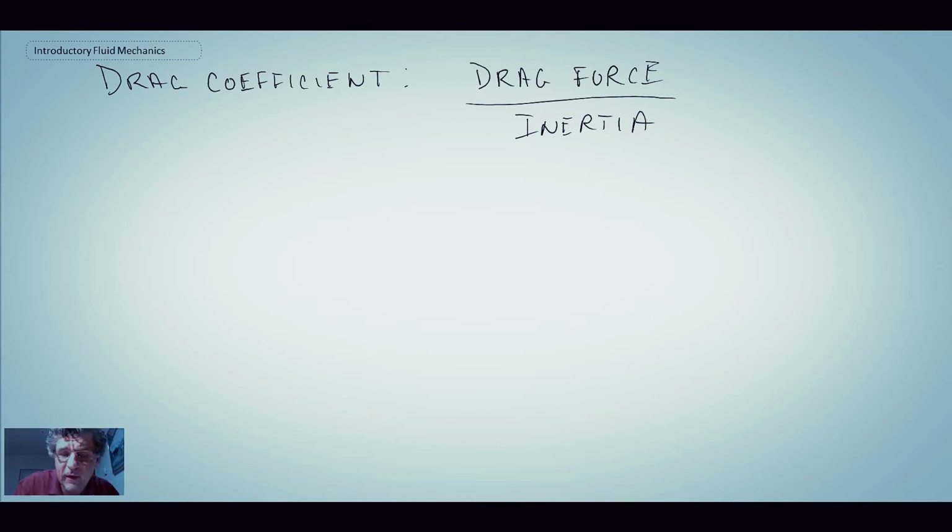We do this for a lot of the coefficients: lift coefficient, drag coefficient, pressure coefficient. But what we do is we take the force itself, and this is one that we studied earlier on when we looked at Buckingham pi, but you get 1/2. You get the dynamic pressure in the denominator. So 1/2 rho, some characteristic velocity squared times some projected area. And this would characterize things like drag on bodies.